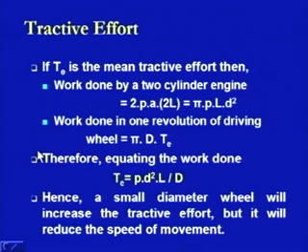That's why the total length governed here is 2L, and this is how we compute the value, and this is transformed into another value like pi p l d square, where d is the diameter of the cylinder or the piston. The work done in one revolution of the driving wheel, here we are talking in terms of the tractive effort which is being given to the driving wheel as Te, and because of this the wheel is moving, therefore there will be a movement equal to the circumference of the wheel, that is pi d, and the work done will be nothing but pi d multiplied with Te.